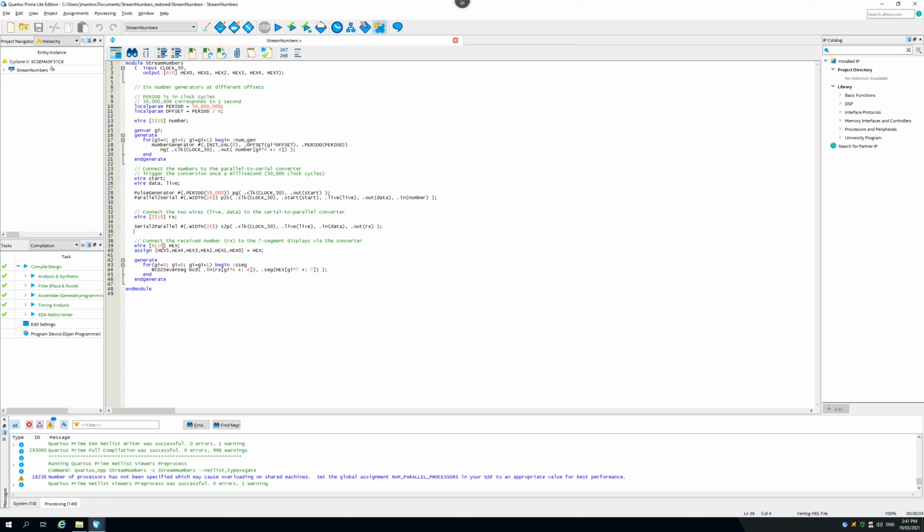It's going to hold 42 bits, and so therefore it can hold all of these 6 7-bit wires here. And all I've done is I've assigned to them the value of hex. So this means that rather than me having to write down BCD to 7 segment, rather than me having to instantiate this 6 times, and each time passing to it hex 0, hex 1, hex 2, hex 3, hex 4, hex 5 by hand, I can now use this algorithmic method to achieve the same thing.